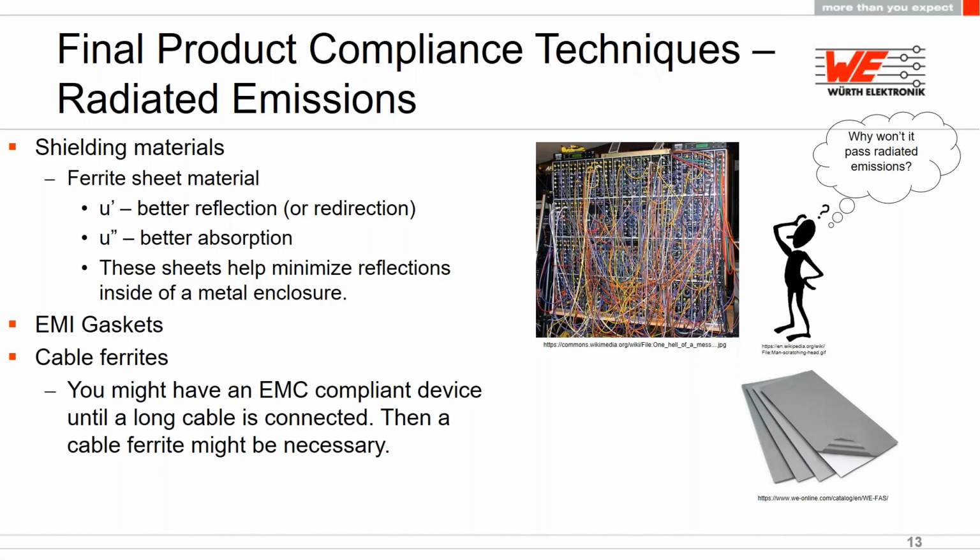Some other techniques for passing radiated emissions. Hopefully you're not starting out with something like this, because I don't know if there's much help if this is your design, but you can start out with some shielding materials. We have a ferrite sheet material that you can use.